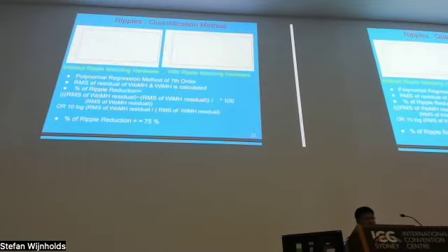So we have used a polynomial regression method of 7th order. Why 7th order? If you go for 8th or above orders, it becomes an overfit. This fit line becomes overfitted, which gives us the wrong result. And if it is less than 7th order, that becomes underfit, and that also is not giving a correct result. So after 7th order regression, we got the coefficients, and after calculations, the RMS of the residual signal is calculated.